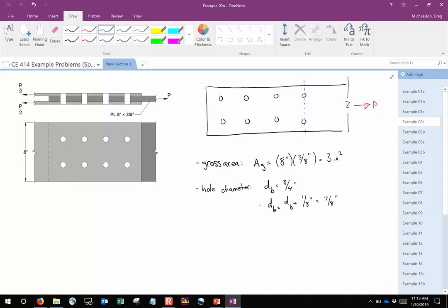So I guess the question is, what's the area of a bolt hole? Somebody tell me. I'm just talking about the formula. What are we going to use? Pi r squared, right? Sounds like a good answer, right? It's wrong, and I'll explain why. You've got to think in cross sections. Remember, the samurai sword or the lightsaber, what's that going to look like?